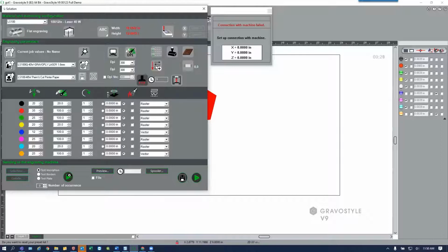Okay. Another new function is in our processing. So here we can select to engrave from the top to the bottom of the material, or from the bottom of the material to the top. So if I'm engraving a material, let's say that is a black surface with a white core, if I engrave from the top to the bottom, then as I'm working my way down the material, I've revealed white crisp lettering that was under the cap, but the debris, the soot, the smoke, as I'm working down the material, gets pulled by the exhaust system back across my nice white letters and potentially could stain those or leave a residue that would be hard to clean off.